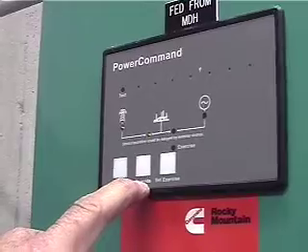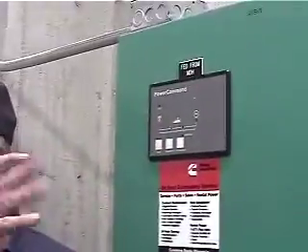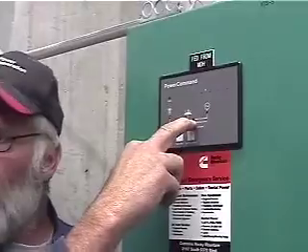Once it goes through that period of time, if you want to override and shut it down, you can push the override button. It doesn't say this anywhere, but this is also a reset button. So if you get one of these lights that's flashing and you don't think it's supposed to flash, if you push the override, it brings it back to the normal state. For instance, failed to transfer. If it fails to transfer, it's going to flash this light right here, saying that it didn't actually transfer.